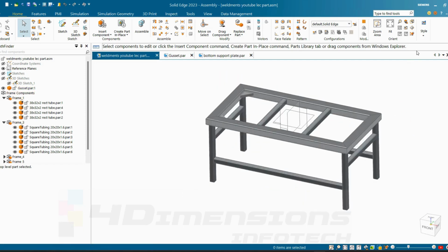It is because the Solid Edge interface supports pattern only when the patterns are made in part modeling also. Those patterns can be reused here. So if we have made a pattern in part modeling only, then we can pattern here. But we have made this assembly structure in Weldments itself, so we have not earlier made any patterns in part modeling. That's why we cannot use the pattern command here.